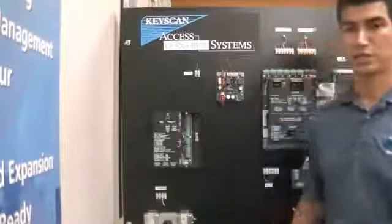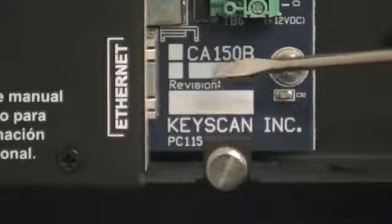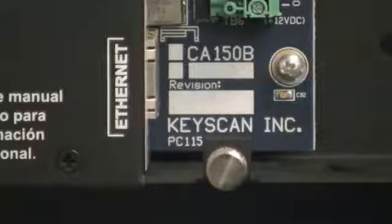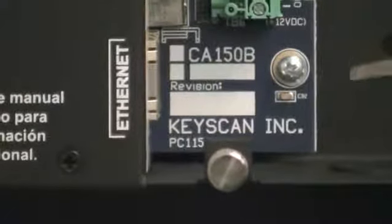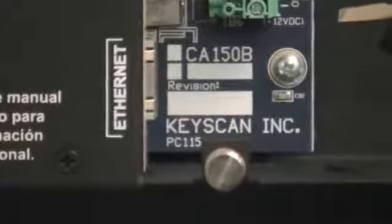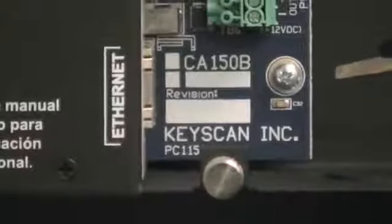Let's now review the connections of the CA150 single door access control unit. This is our PoE Ethernet connection for the CA150. The PoE connection provides power to the CA150 unit and all of the devices for the door that are connected to the CA150. There's approximately 680 milliamps total current available for these devices.